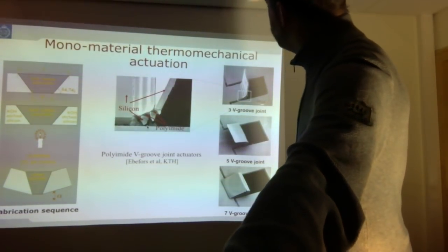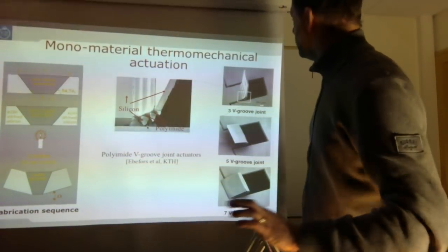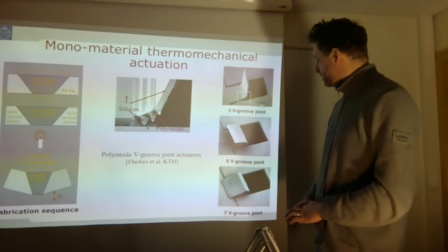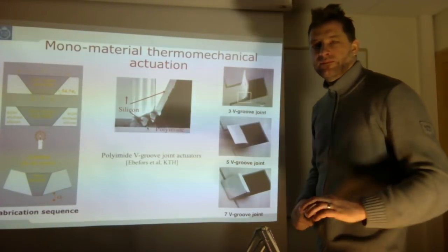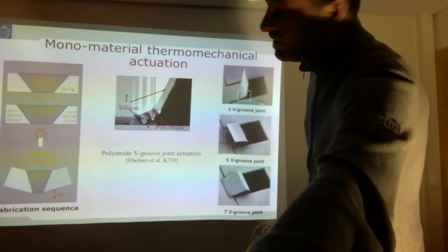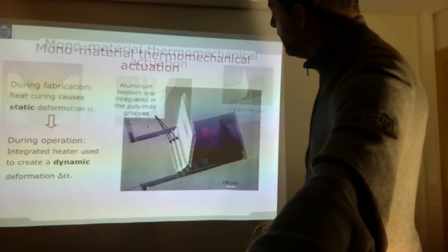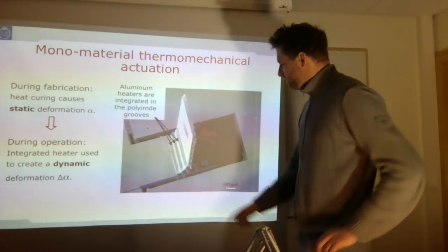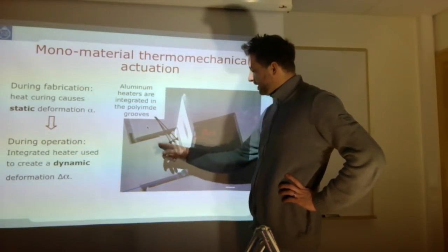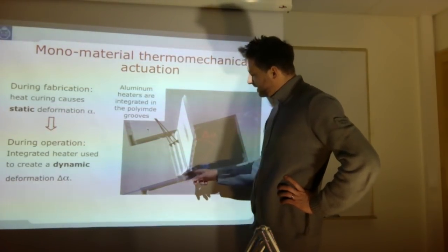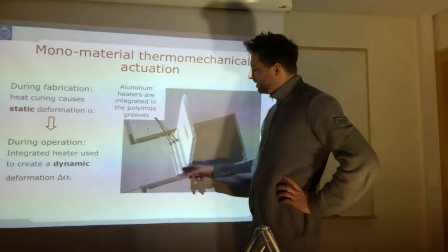So, is this an actuator? No, this is not an actuator. This is just an out-of-plane structure. But to make it actuate, actually, I will have to make it move. And how do I do that? Well, what I can do is integrate, you cannot see that here, aluminum heaters underneath this polyimide.